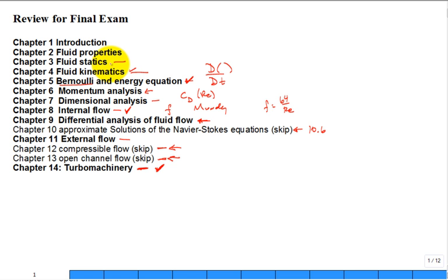Fluid statics. You'll see you continue to go back to what a simple manometer is. You don't get away from manometers very far. We talk about pressure in air systems as inches of water column. That's referring to pressure measured by a manometer and how high that height is in a manometer. You may think, I've seen manometers, I know manometers, that's great. Master manometers,